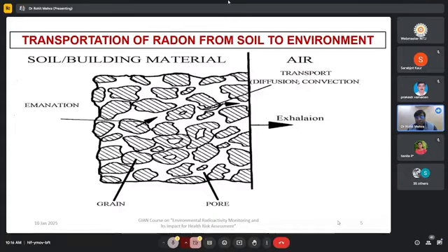So what is the reason? Sometimes some researchers are confused that it is from 100 to 300, and if it is beyond 300, it will be dangerous. It is not dangerous. It will add to the exposure. There will be more exposure to natural radioactivity for the human populations residing in those buildings which have more radiation exposure in terms of radon, that is, more than 300 becquerel per meter cube. And one thing is very important.